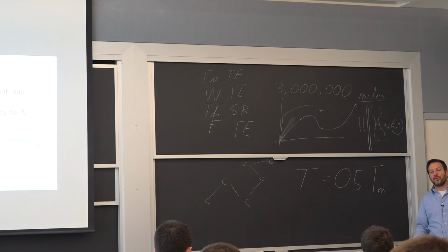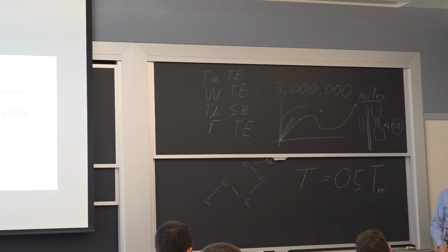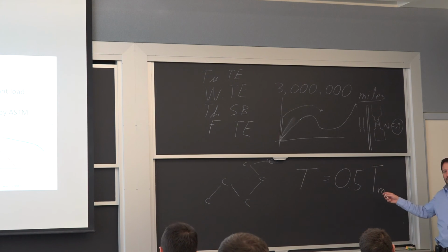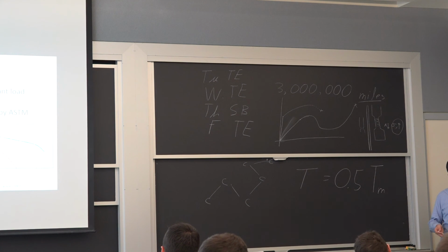It will matter if we're building an engine, for example, but with respect to just a structural application, that's fine. It will matter if you have a fire. World Trade Center that we were talking about, so there's going to be a point where it's becoming softer, and just under sustained load, it's just going to start to creep by a number of mechanisms.